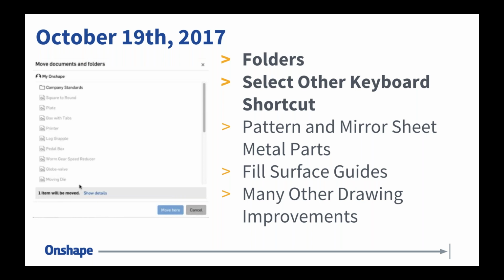If you're designing symmetric sheet metal, anything, you oftentimes want to design the half and then mirror to create the whole. And in the past, you couldn't do that and still get a flat view, right? A flat pattern. So you can now mirror or pattern sheet metal parts and add them back to the original, merge them with everything and get one flat view. And that was a limitation in the past.